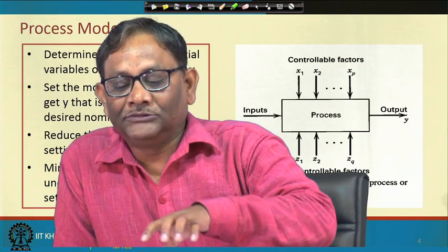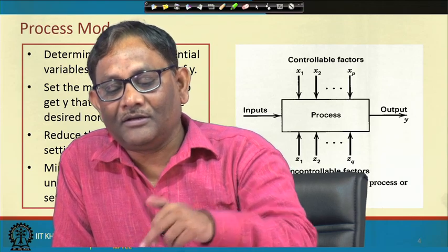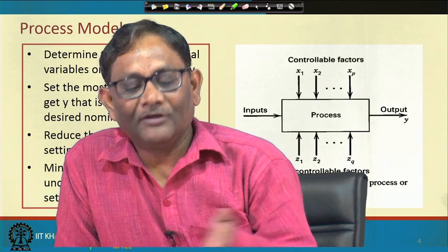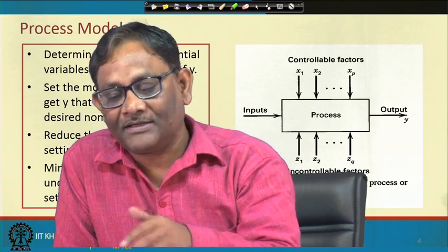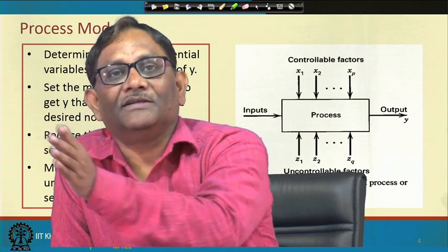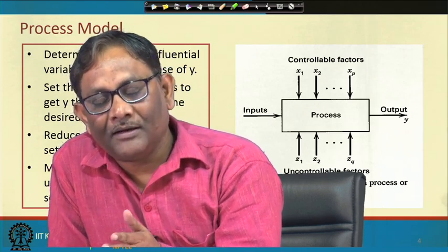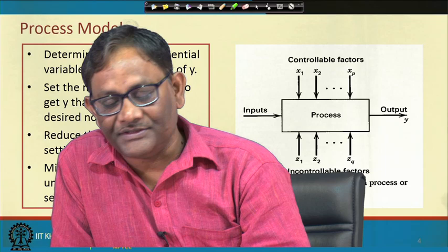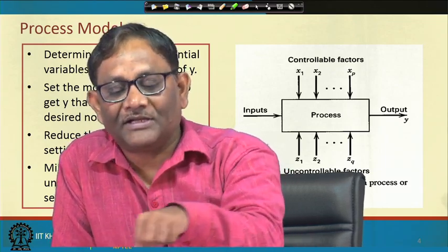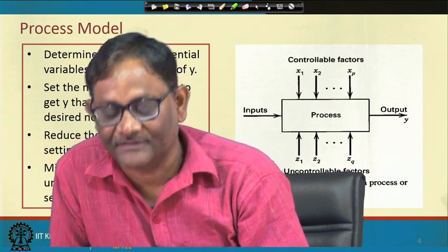So, DOE is applicable, or you do experiments here, in how you manipulate the controllable factors and also sometimes inputs in such a manner that the output quality, or the response, will be at the desired level, or the variability of the output will be in the desired range, or you want to know the relationship between the output and the controllable factors, or sometimes also the noise factors.